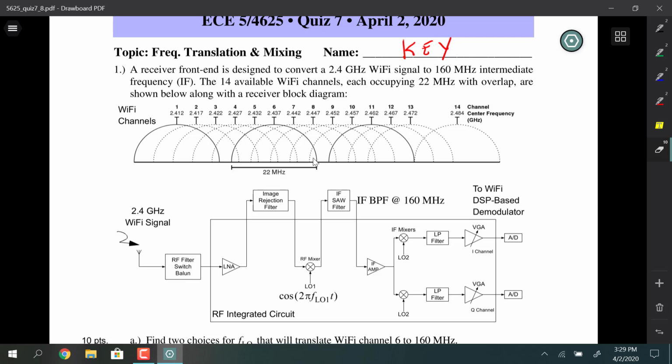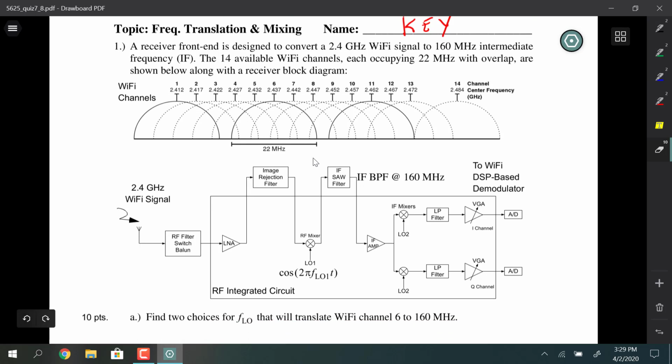So these are the original Wi-Fi channel allocations. They're each 22 megahertz wide. They overlap each other. I took this right off of Wikipedia, I believe, for Wi-Fi. And you can see how if you're going to coexist, and this is actually part of what the unwritten lab for the comm lab was going to have you do: go with the antenna and the FieldFox and sit near different buildings on the campus and just see if they're abiding by this spectrum allocation.